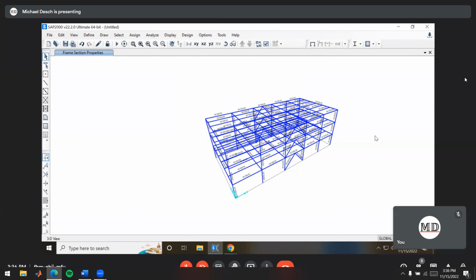And because we imported all 4 layers into here, we have 4 groups. And if we select the W18 by 97 group, that winds up being all the columns, because those are the numbers I assigned to that layer in AutoCAD, basically. So it's not like trying to suss out what each of the numbers should be just from the geometry here. It's because that's how I modeled it in the DXF.